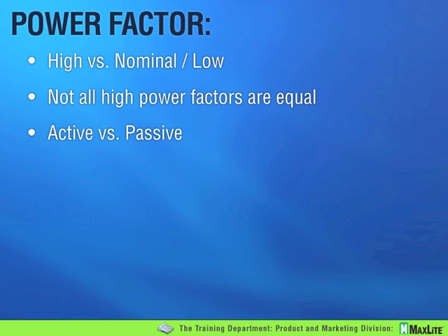Active power correction also markedly diminishes the total harmonics. Harmonic distortion is another issue, and active power factor pretty much eliminates that as an issue. And it automatically corrects for AC input fluctuations, which is normal. Certainly, for the most part, active power factor correction products are also dimmable. So there's a lot of advantages, particularly to the utilities, for active power factor correction.